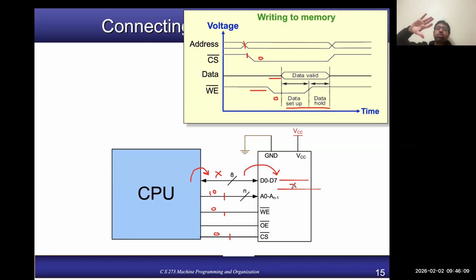So the takeaway here, you don't need to worry about the sequence, but you just need to know that you cannot drive all the required values on all those lines at the same time. There is a delay between them when you place the required values, and there is a reason behind having that delay. The reason is that the address needs to be first decoded by your address decoder, and the amount of the delay is specified in the datasheet of each memory chip.